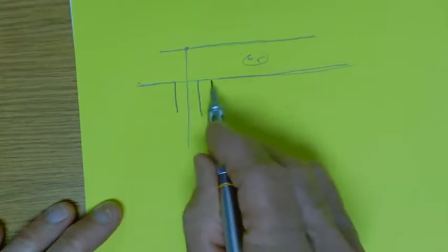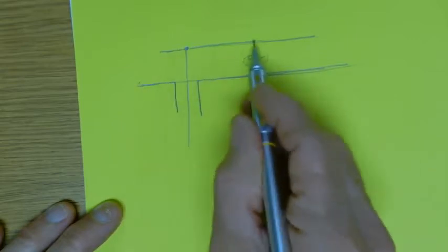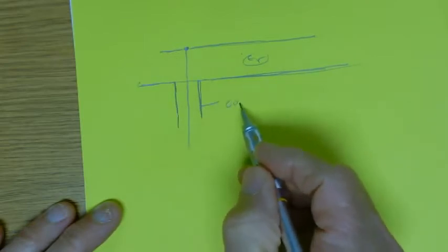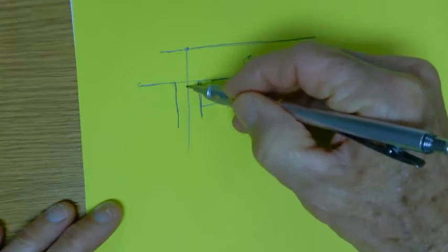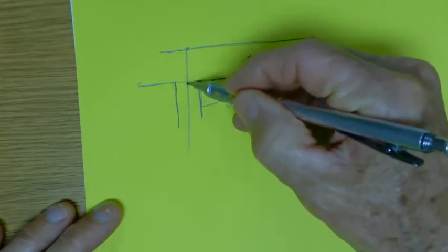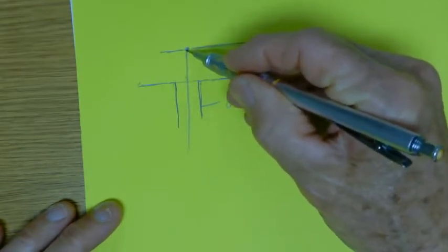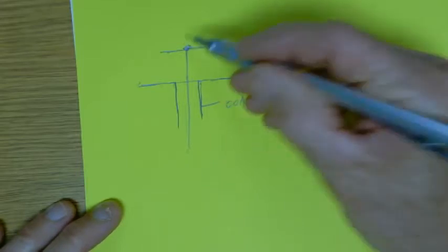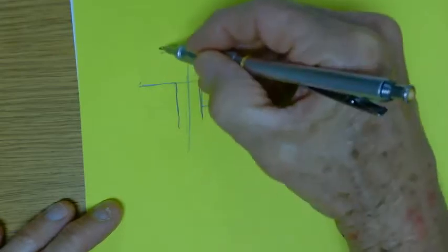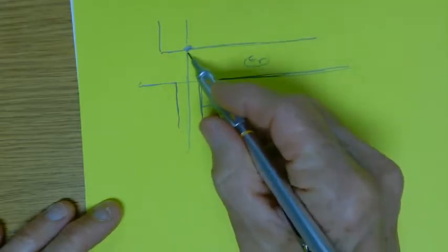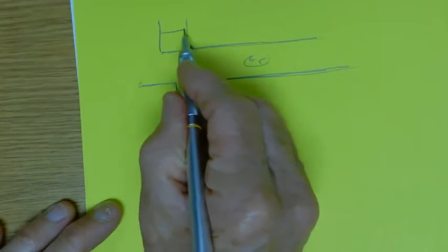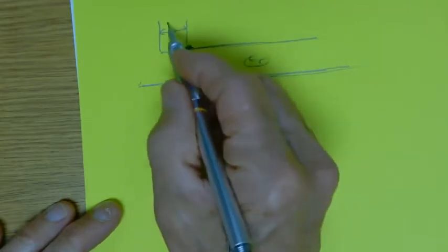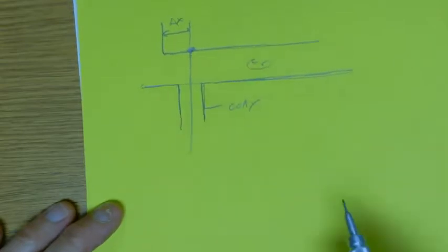Epsilon relative. This is the ground plane. This is the patch, and this is your coax, and this is the center conductor coming up. So you extended the coax center conductor up here. You drilled a little hole. You might have twisted this over and then put a blob of solder. So now you're feeding the patch. This is a so-called probe-fed patch, and you've moved the feed point over some distance, delta x, from the edge.